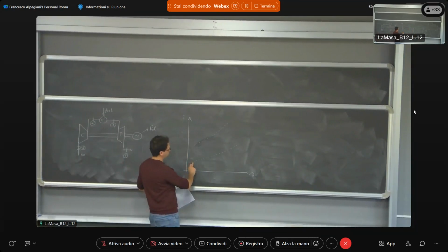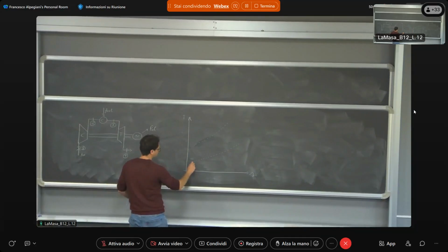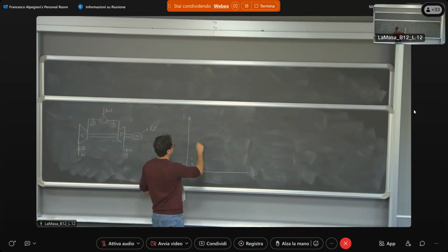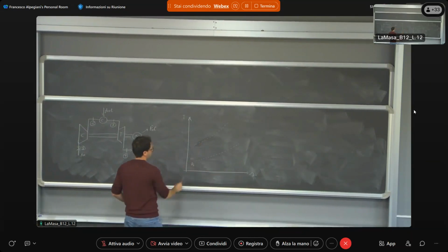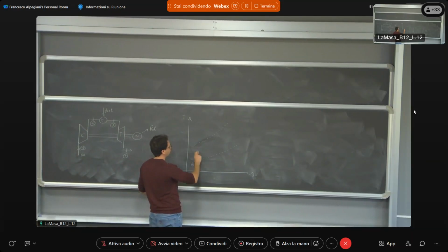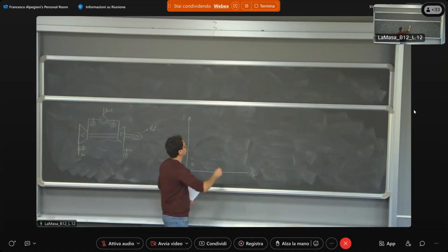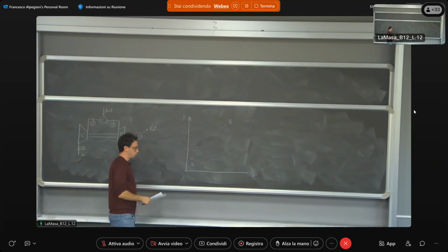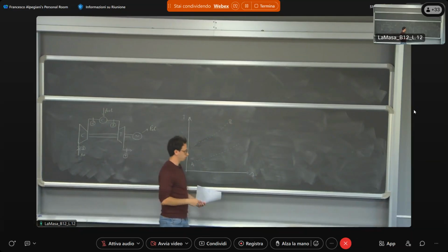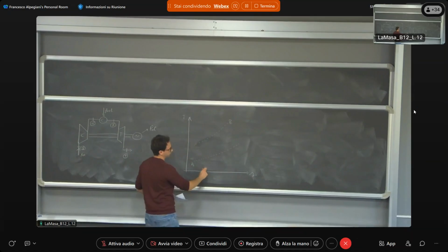This will be the pressure at the inlet, so P1, the isobaric line equal to P1, which is the ambient pressure. Then we have a compression of the air, and we go to P2. We can go to P2 in two different ways, with an isentropic compression, in which the entropy generated is null, so it is a vertical line. So let's do it like this.